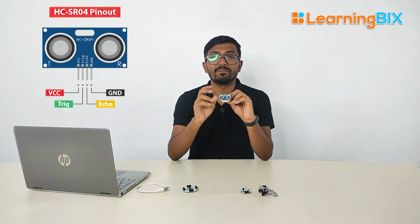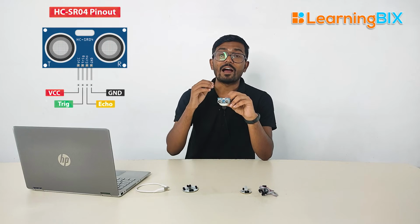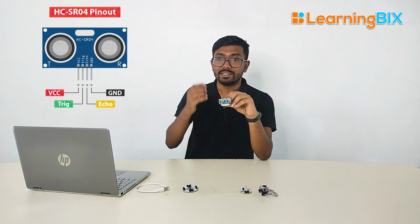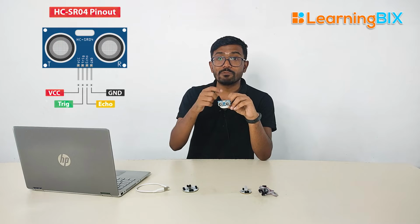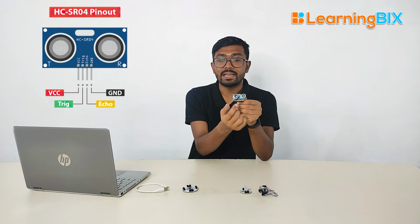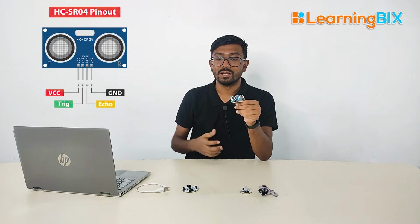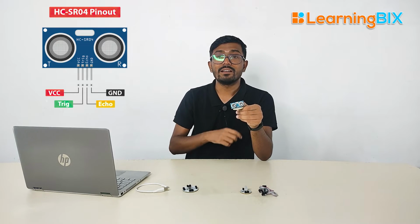Here the transmitter will transmit the ultrasonic waves, and after striking a surface or an object, they will get reflected back, and the reflected waves can be received by the receiver. If you look closely on your side, you will see that we have a T and an R written there. T stands for transmitter, R stands for receiver. So T will transmit the ultrasonic wave which will be received by the receiver.